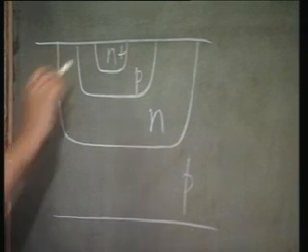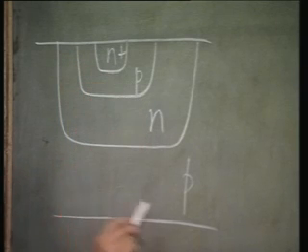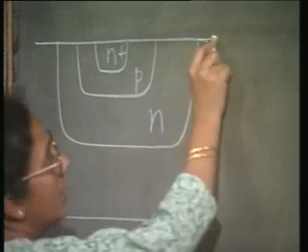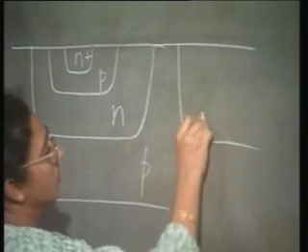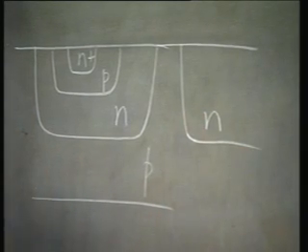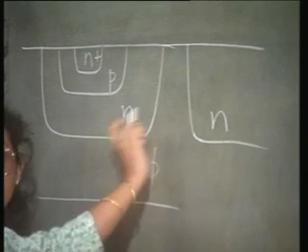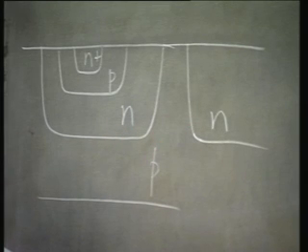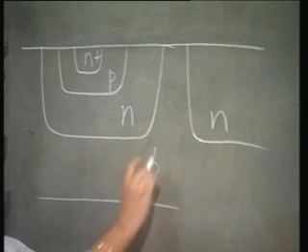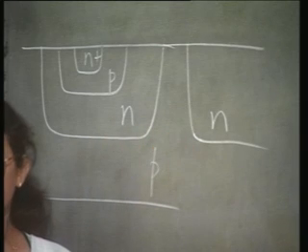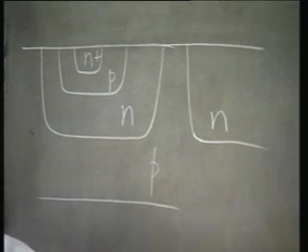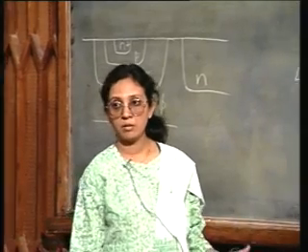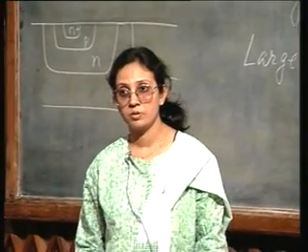So, I have emitter, base, collector, all of them housed in the p-type substrate, and I have the next adjacent transistor housed in another N diffusion. So, you see they are automatically isolated. I do not have to have this large p isolation diffusion.